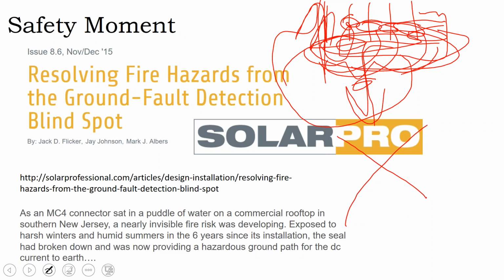And so we've had an instance where the way that traditional inverters were monitoring ground fault detection has a blind spot in it. This is for what are called grounded inverters, which connect their negative DC circuit to ground. They have a blind spot where small failures can elevate that grounded circuit, and if your ground is rising in voltage and your ground fault detection is monitoring the difference between your negative circuit and ground, it could cause a blind spot. In newer inverters, called ungrounded inverters, they've taken out that negatively grounded point of reference in the DC ground fault protection circuit and resolved that blind spot issue.